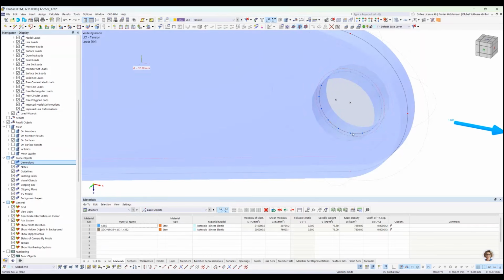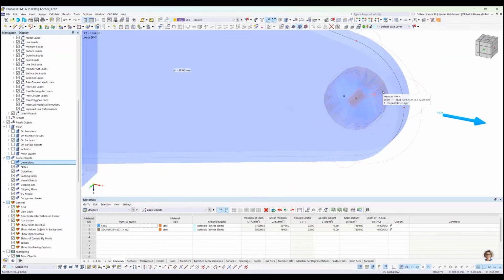then I choose a surface here where you can calculate with the diameter and pi the surface of the cylindrical area, and then model some beam elements which would have the same area here. This is our recommendation how to model this kind of screw connection, to have some effects regarding displacement of the hole itself and let the force find its way into the connecting plate here.